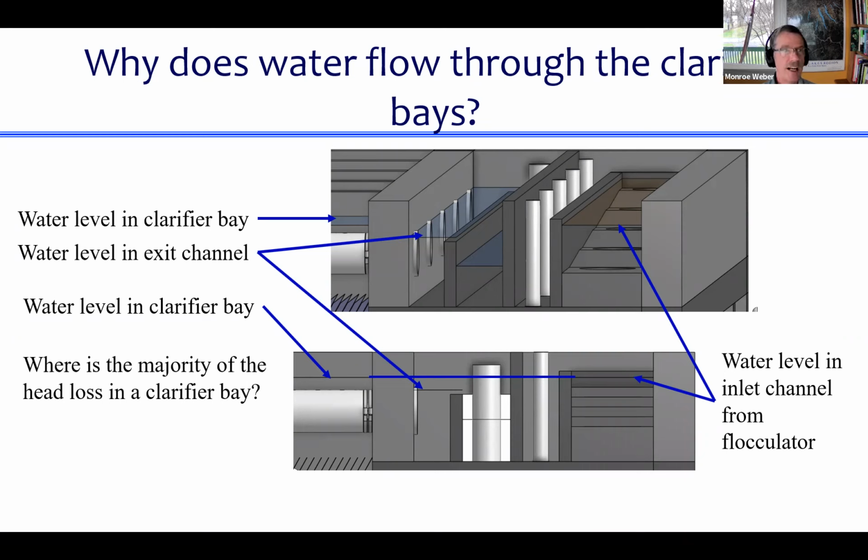And there's head loss for exactly the reason that Dan mentioned. There's a flow expansion. And so the kinetic energy that the water has when it's going through the contraction in the orifice largely gets lost as it's flowing into the pipe. And so we lose energy there. And so that's one place where there could be head loss. The other place that there could be head loss is major or minor losses in the pipe itself.